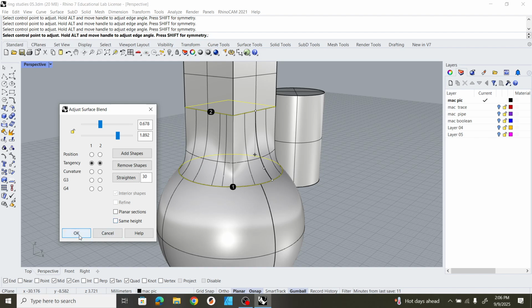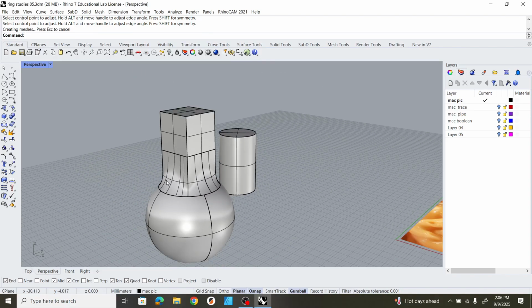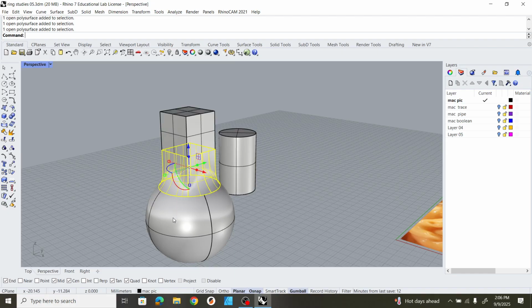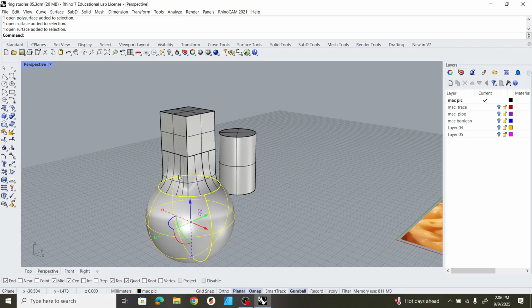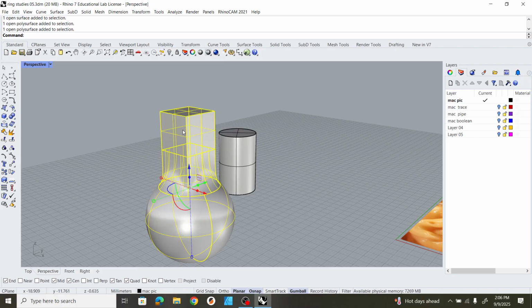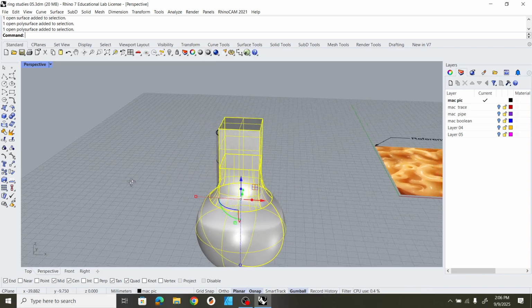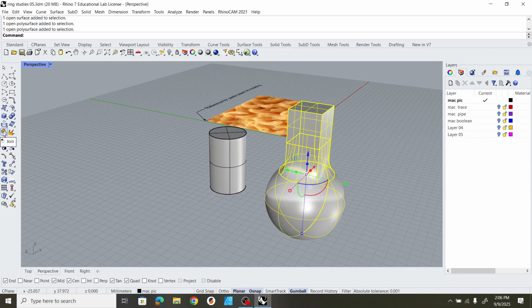Yeah, good question. So they might be three separate objects. Let me check. Once I've solidified what I want the blend between those two shapes to look like, I can say okay. And if I select it, now these are three separate things, but I can take them, and as long as I did everything right, I should be able to hit that join button. So join works in instances like this. Boolean would work if these were all closed solid objects.